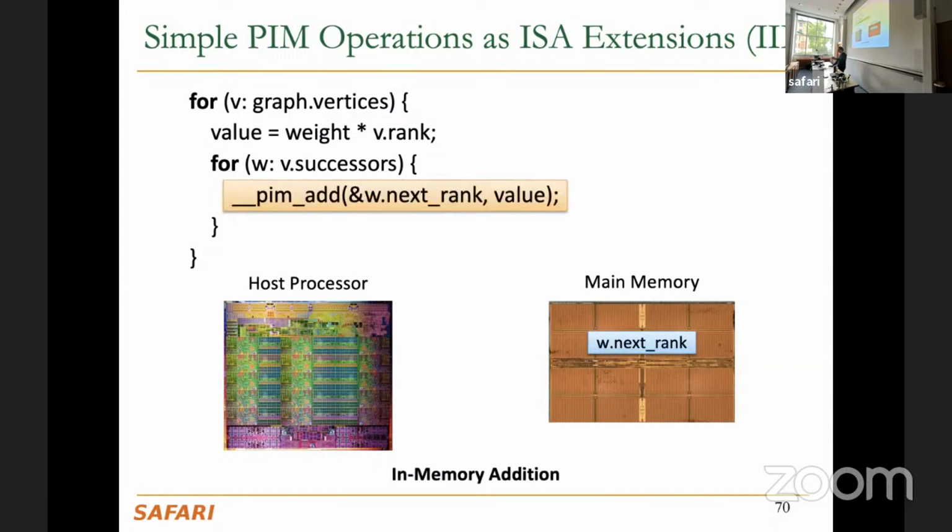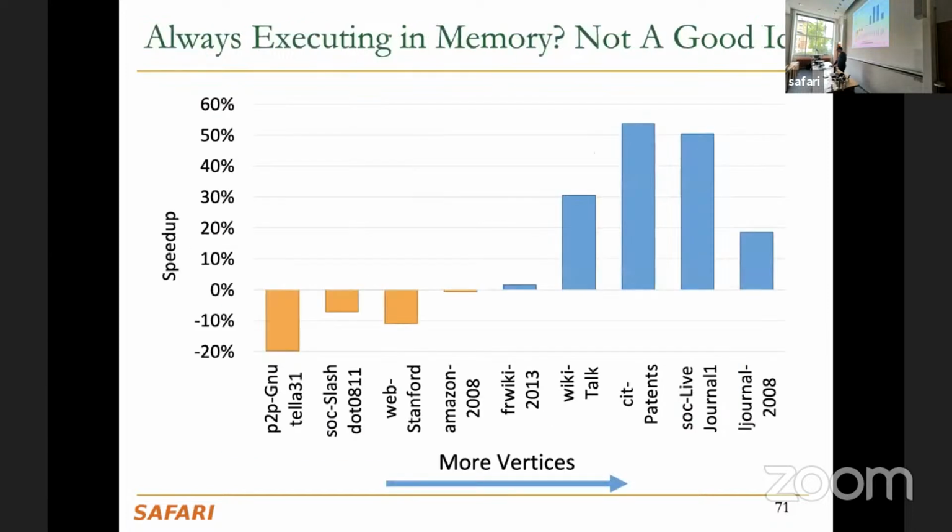Now, if you actually ship it to the memory, this translates into a PIM instruction. You send the value to the main memory, and if your interface allows it, you send only 8 bytes. Interfaces are a different issue, but ideally, you send only 8 bytes. That sounds good. That's a 16x reduction in terms of memory bandwidth. And if there's no locality or little locality, this sounds great because you don't need caches anyway. Okay, that's the idea basically.